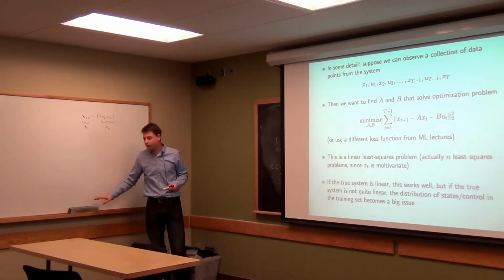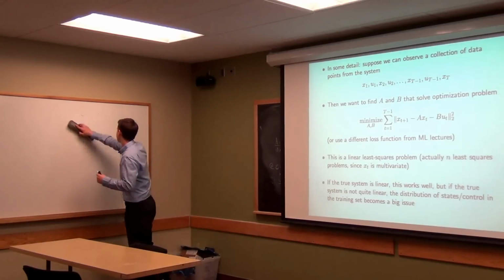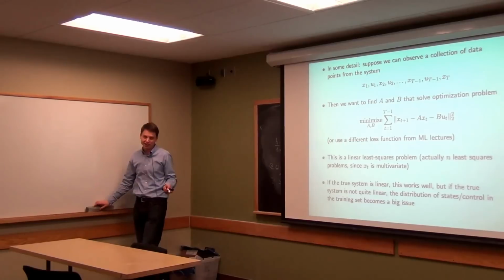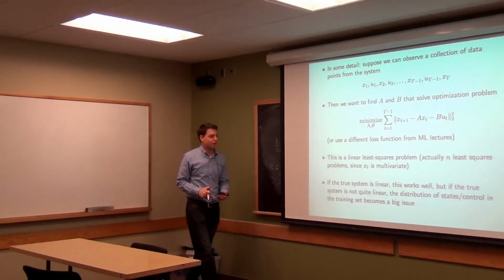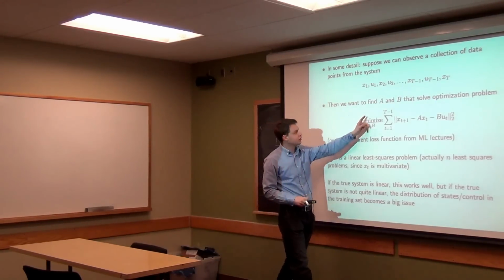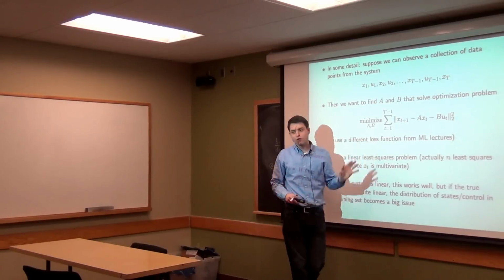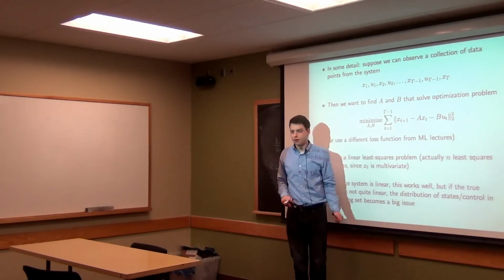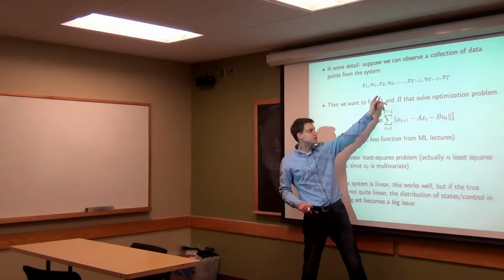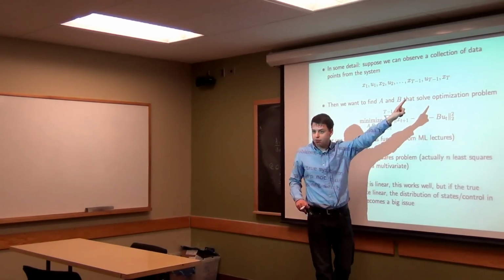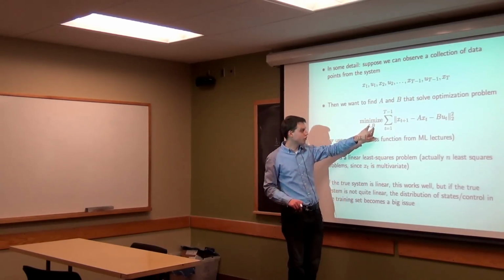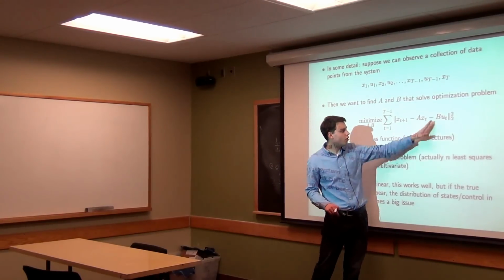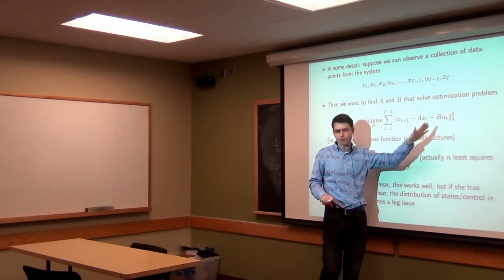And that is just a machine learning prediction then. In the simplest case, let's just learn a linear model. If we start doing nonlinear models, then we have nonlinear control tasks, which get a lot harder. So let's think about learning a linear model. The idea here is that, say, for least squares, you would want to find the A and B that solve this optimization problem. You have some sequence of t observations you've made, and you want to minimize over a single A and B: what is that single A and B that minimizes the sum of all these errors?